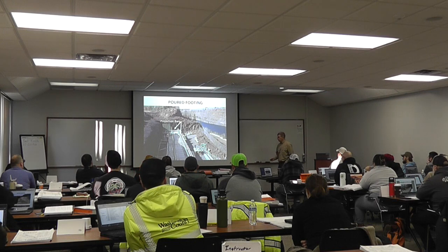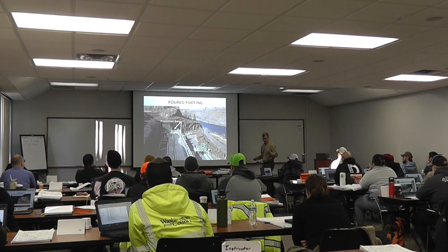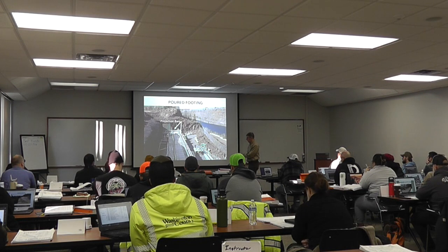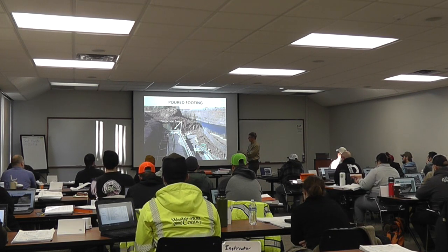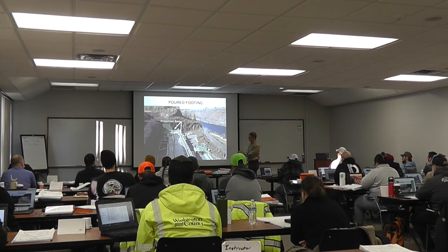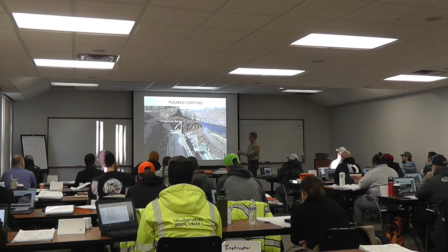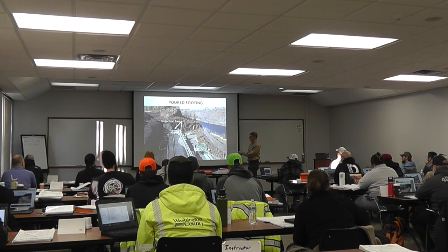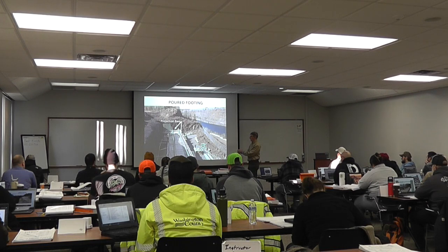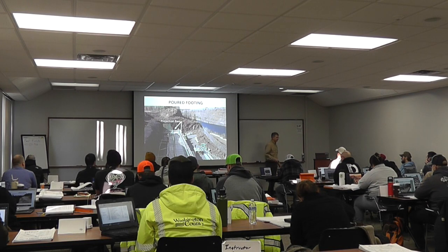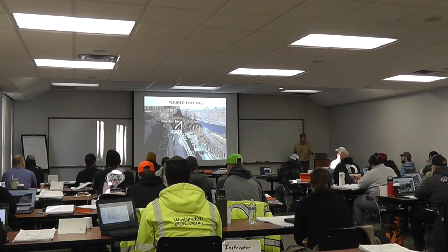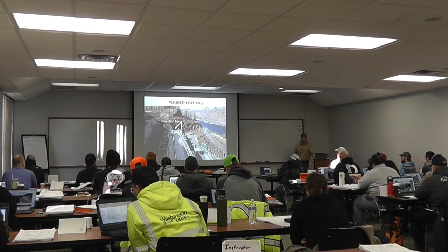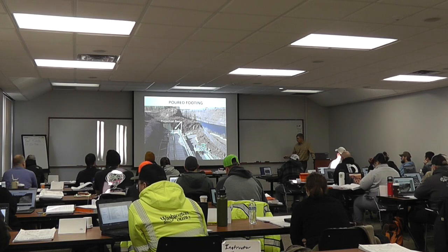So here, whether it's a spread footing, a pile supported footing, or whatever, we want to know what is the distance that we're supposed to come out of the footing. Sometimes it's simply what is the lap length that we need. Other times this bar might continue up, and then the next one might lap starting 5 feet up, just to try to minimize some steel or whatever. But pay attention to that, and obviously pay attention that they're also in the correct location.